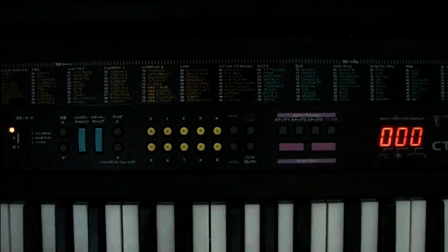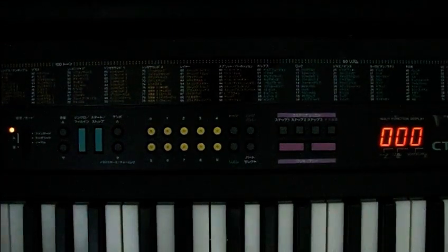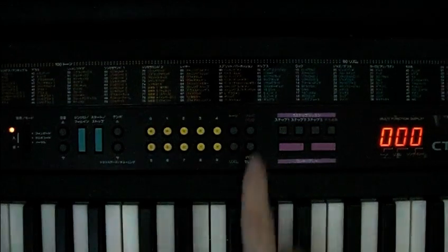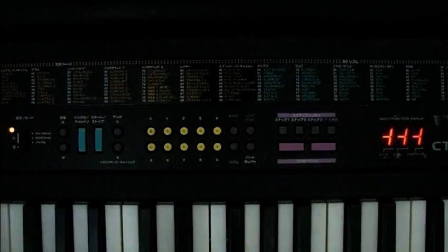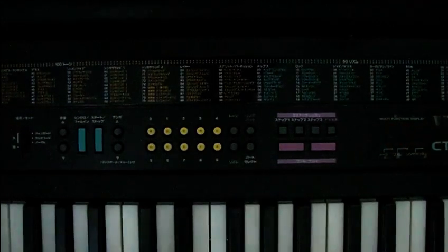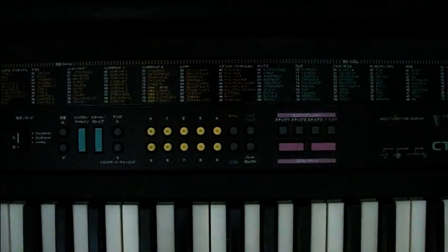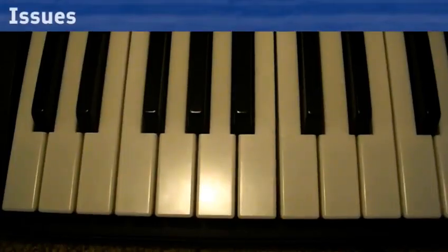Press Song Bank. You should see zeros on the screen. Plug the DC jack back into the unit. Press Song Bank. You should see ones on the screen. To test the software power off function, press Part Select. The unit should turn off. The diagnostics are complete. B over C is treated as a valid user chord.